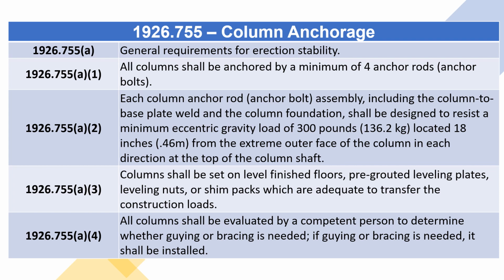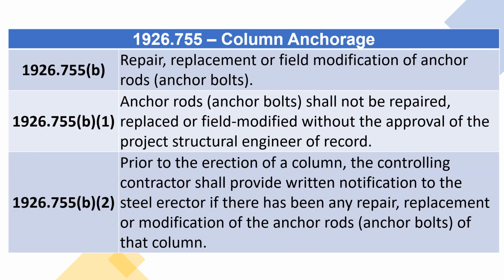1926.755 A4. All columns shall be evaluated by a competent person to determine whether guying or bracing is needed. If guying or bracing is needed, it shall be installed. 1926.755 B. Repair, replacement or field modification of anchor rods (anchor bolts).